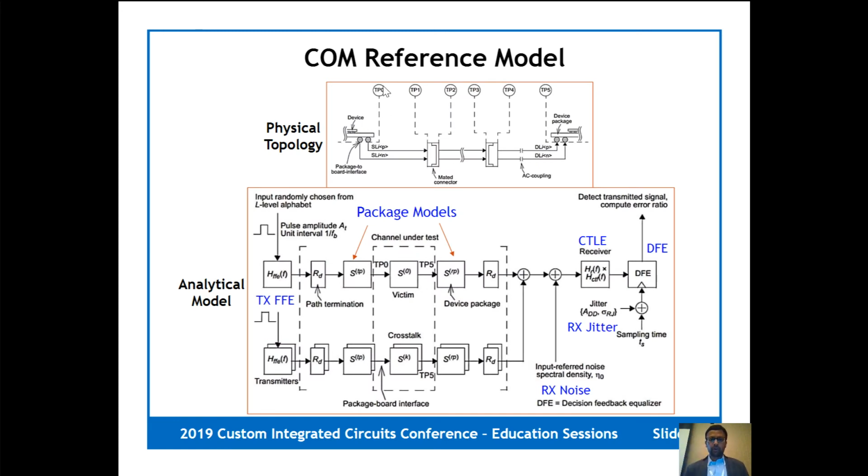So the reference model itself that's used for the channel operating margin computation essentially converts this physical topology that you have into a more abstract analytical model, which includes models for all the relevant SerDes components for signaling analysis, like the TX-FFE, and on the receive side, the CTLE and DFE, and models for all the components of the intermediate channel.